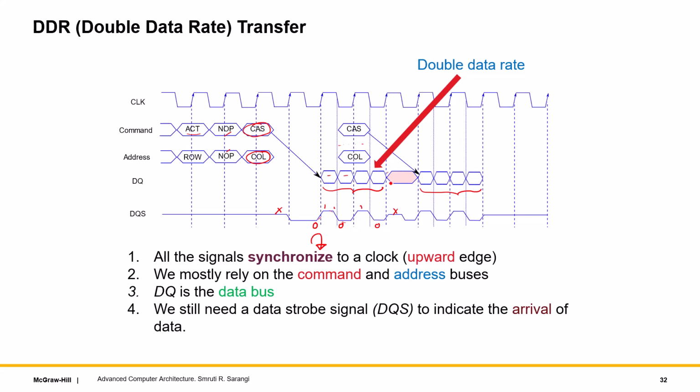A fallow period is a period in which nothing happens, and the reason for doing that is to let the voltages stabilize and clocks to resynchronize and so on. And after that, the new command takes effect. So we clearly issued this command as soon as we could, and then the new transfer takes effect based on the column value specified over here.